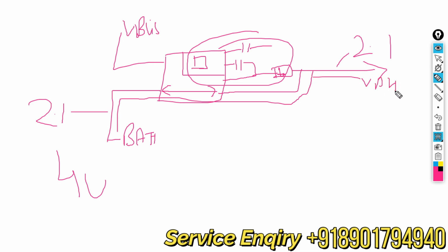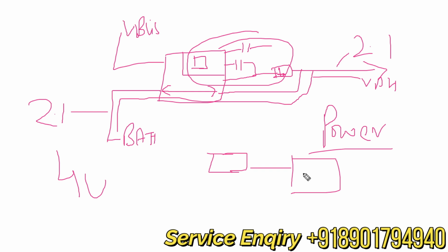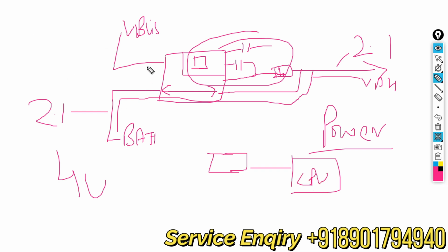That's how your power IC gets a proper voltage, right? An input, a VPH. That's why the power IC generates the buck voltages, and after the buck your CPU turns on, right? But there is a leakage on this IC on the VPH, so that leakage drops the current and the phone does not turn on. Clear? I hope you get my point.